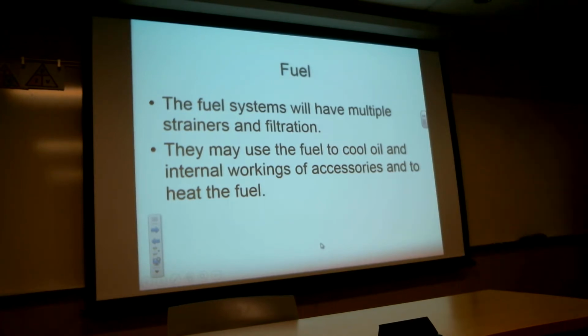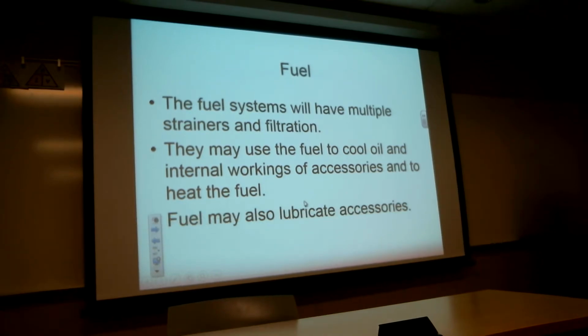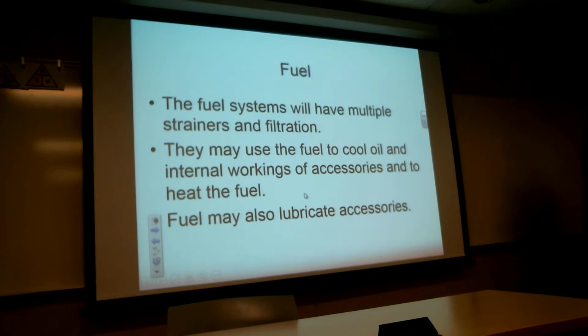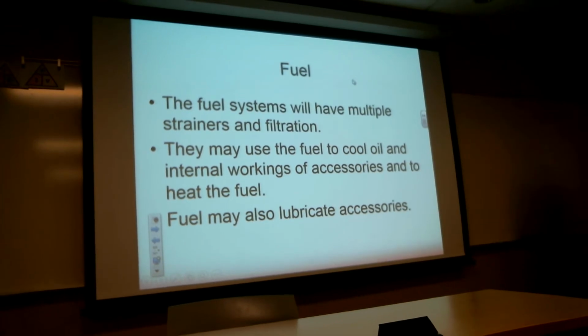We also might use fuel to cool things. We might use it for muscle to operate bleed valves, for stator vanes. I'll talk about stator vanes next week, I think. So we can use fuel as a hydraulic fluid. Works really well. We've already got it on the engine. We can also use it to heat the fuel. You can use it to lubricate accessories, drives, like in the gearbox and generators. So fuel is kind of a handy thing to have inside, just as an accessory on the engine itself.